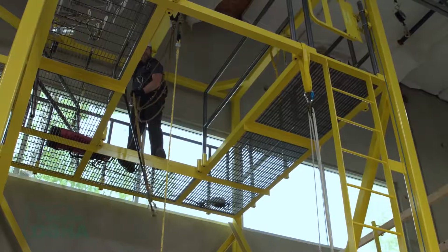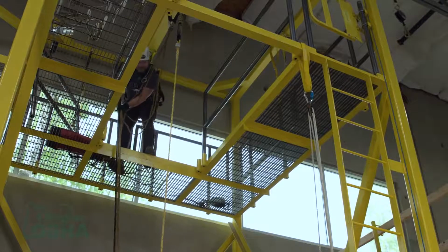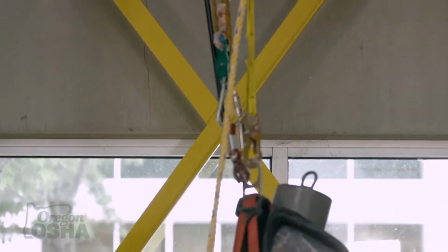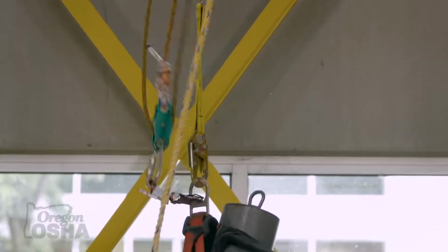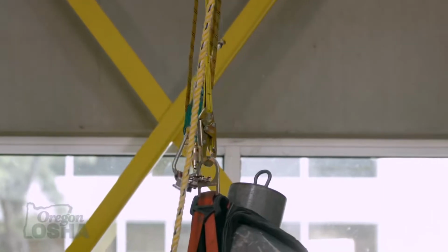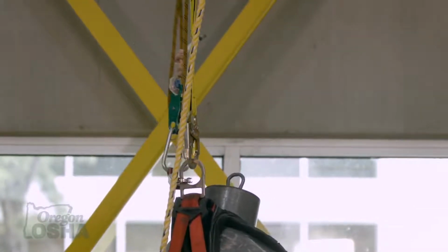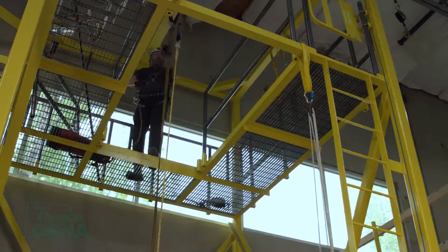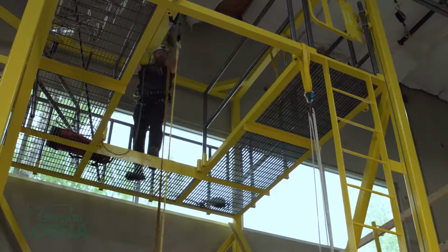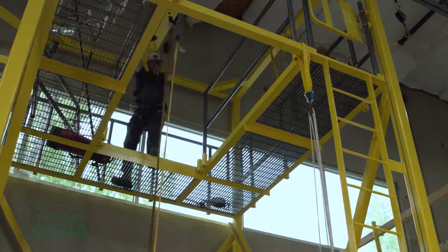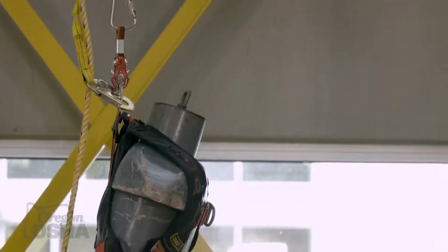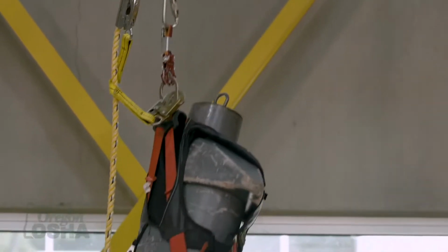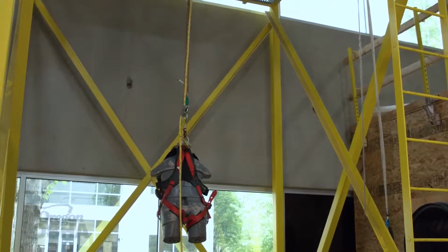So this little device is just a remote device that is designed to attach to the rope so that I can remotely attach it to my worker's D-ring, get that attached, get it popped up here, get my pole out of the way. Then we're going to start pulling slack out of this thing. We're going to raise him up just enough so we can get him disconnected from his lanyard, because you don't want to just cut it. And we're just going to bring him up a bit. Just enough to get some slack in his anchorage or his lanyard.